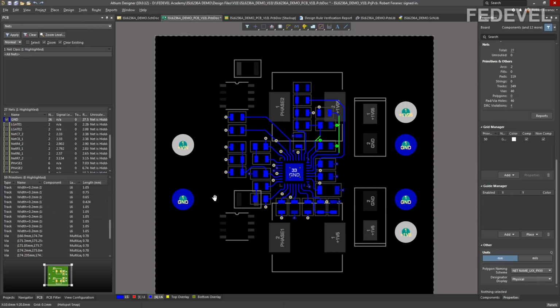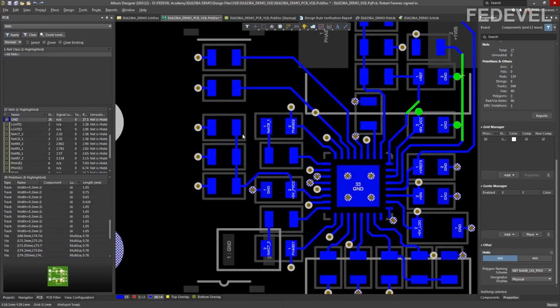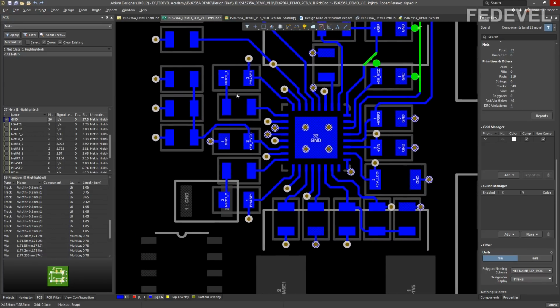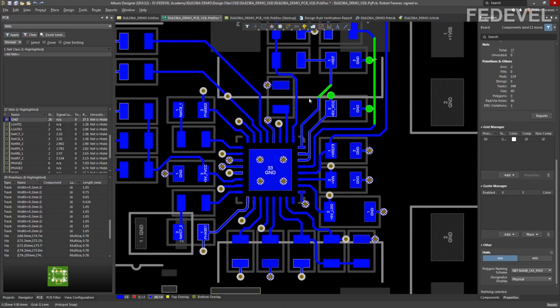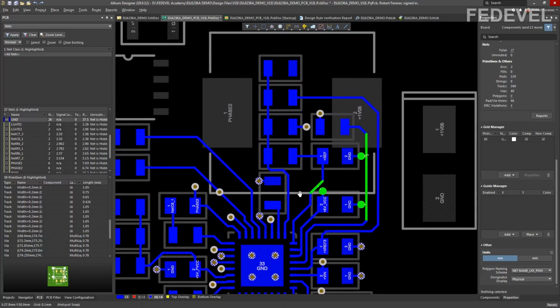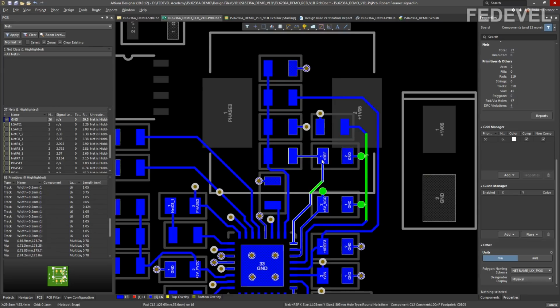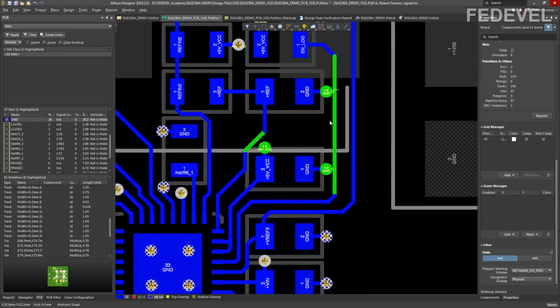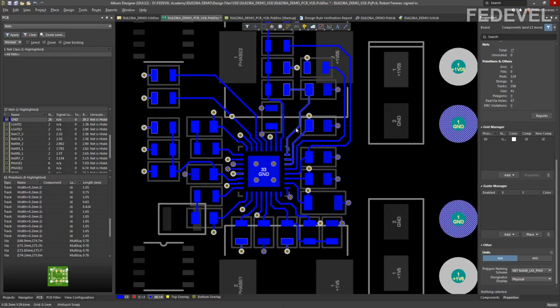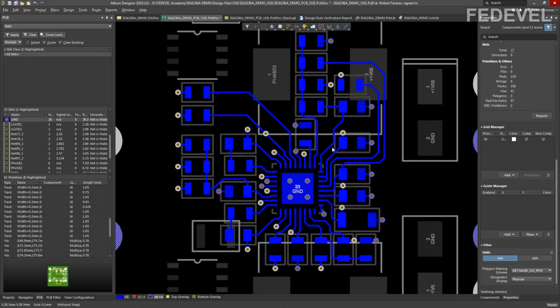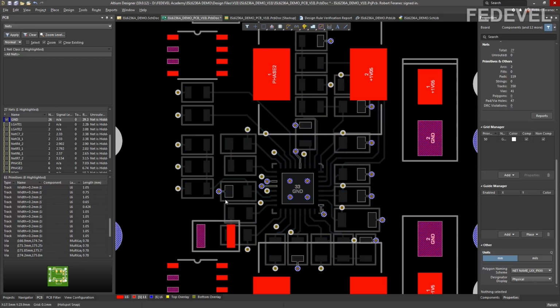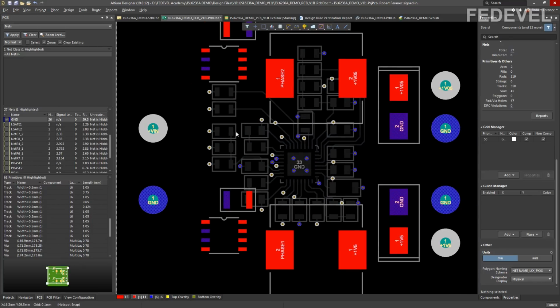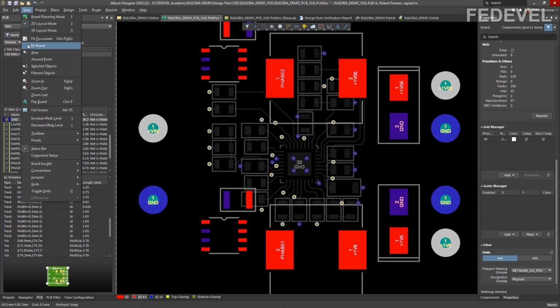Double check if you have connected all the paths on the bottom. If you missed something, don't worry, we will find it a little bit later. But if you see something, you can connect it, for example, here. And also, we can very easily clear these errors. Just move it a little bit. Perfect. We can go on the top layer, left click on this layer 1 tab, and we can connect the paths which are here on the top layer.